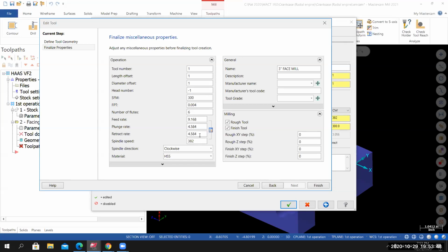If somebody else is writing the program and you're setting up the job, there's a good chance there might be a dedicated face mill to that machine, and the programmer knows what tools are usually used in that machine. I've been in shops where tool 1 through 15 never change because they're always there, and the programmer has a tool list for that specific machine. Does that make sense?